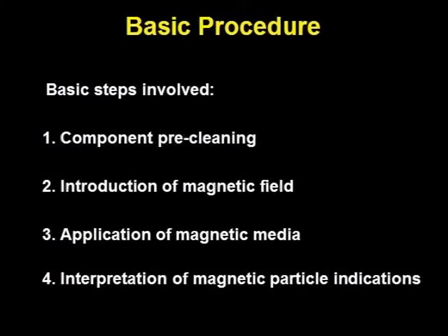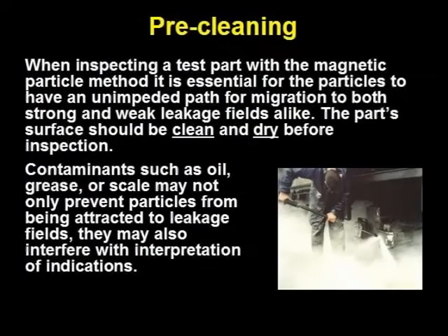Much like penetrant testing, magnetic particle inspection is a process. The basic steps are also similar. The component is cleaned and magnetized. The magnetic media is applied, and the indications are interpreted.